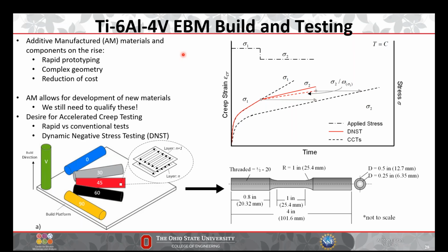And there's a couple of reasons, and some of them are like rapid prototyping, right? You can build these very quickly and do studies on them fairly quickly using complex geometry. So you can 3D print basically any part geometry you want, things that you couldn't do with conventional machining even. And as a sidebar, I believe GE right now is using additively manufactured fuel nozzles in their engines.